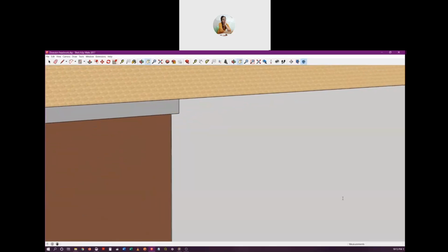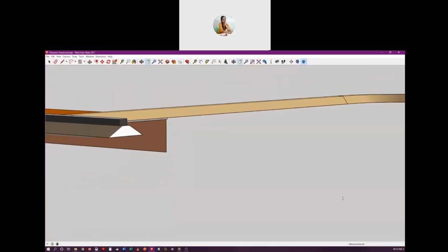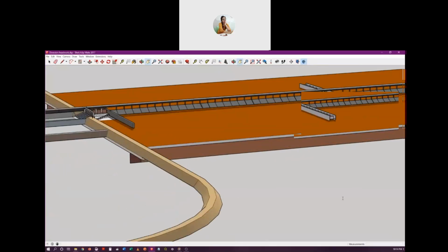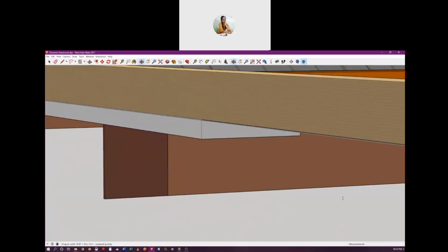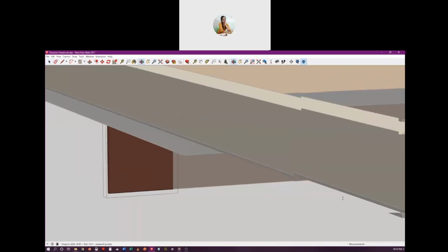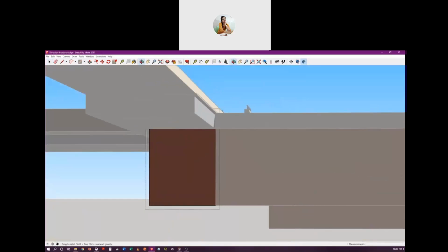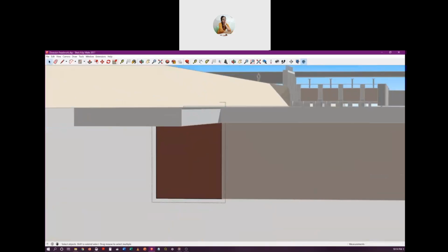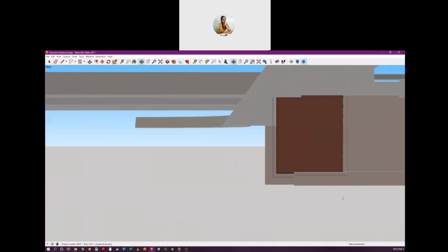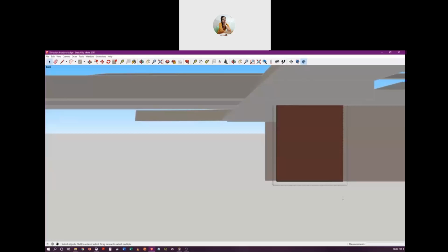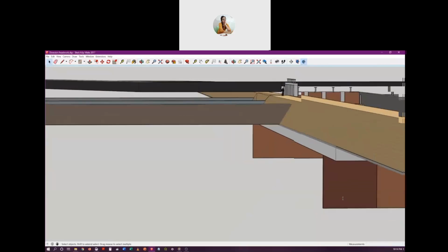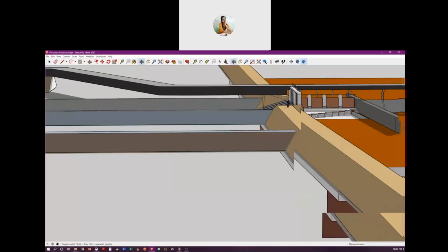And that can be prevented by extending these cutoffs to a considerable length and inserting them into embankments, so that when water tries to take this sideway, it also has to again go through this longer path, because there will be cut off in the horizontal direction also, and therefore the leakage will be reduced.